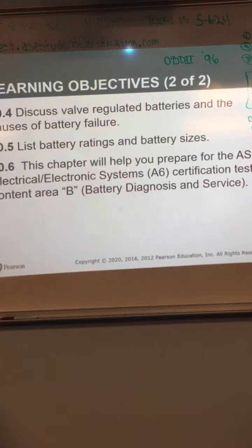You can just start it every week and let it run. If you're gonna do that, at least let it get up to operating temperature. Don't start it for 5 seconds or 2 minutes, okay? Give it time for the battery to charge and the fluids to circulate. If you don't wanna drive it, that's fine, but at least start it once a week. Okay?